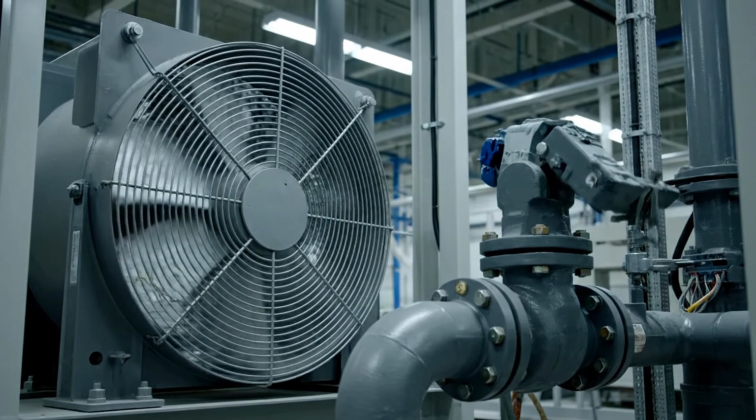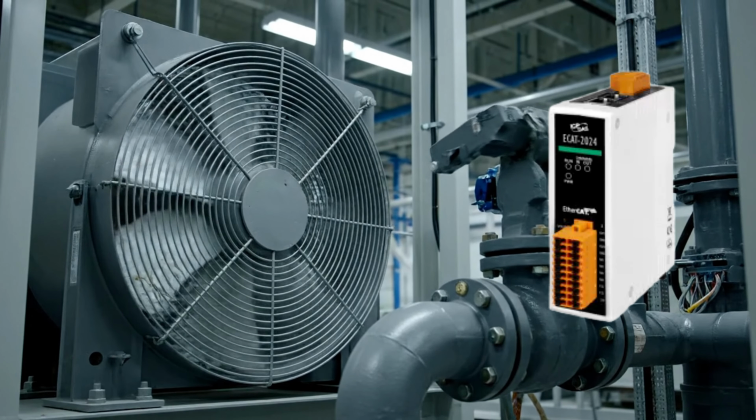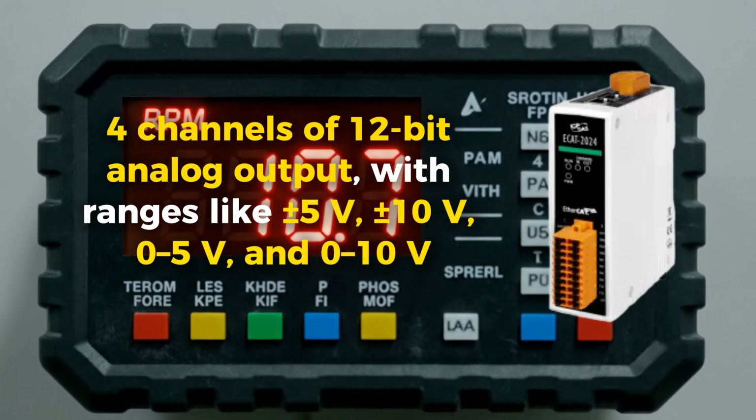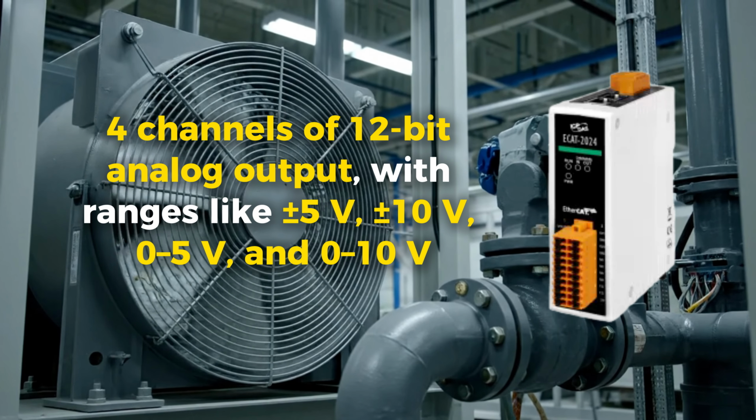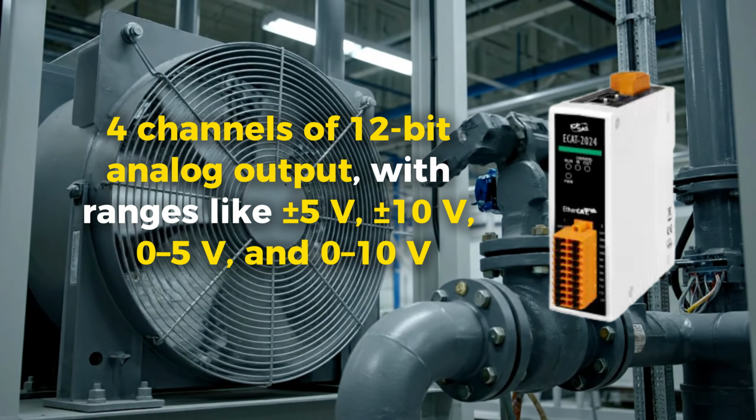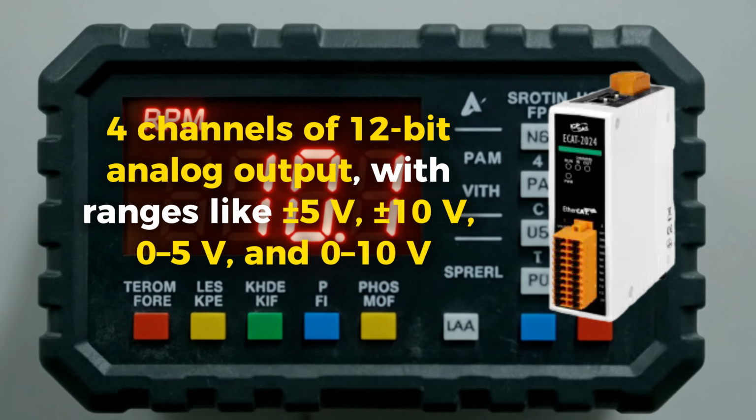Then, if you need analog output signals, the ECAT 2024 provides 4 channels of 12-bit analog output with ranges like plus or minus 5 volts, plus or minus 10 volts, 0 to 5 volts, and 0 to 10 volts.